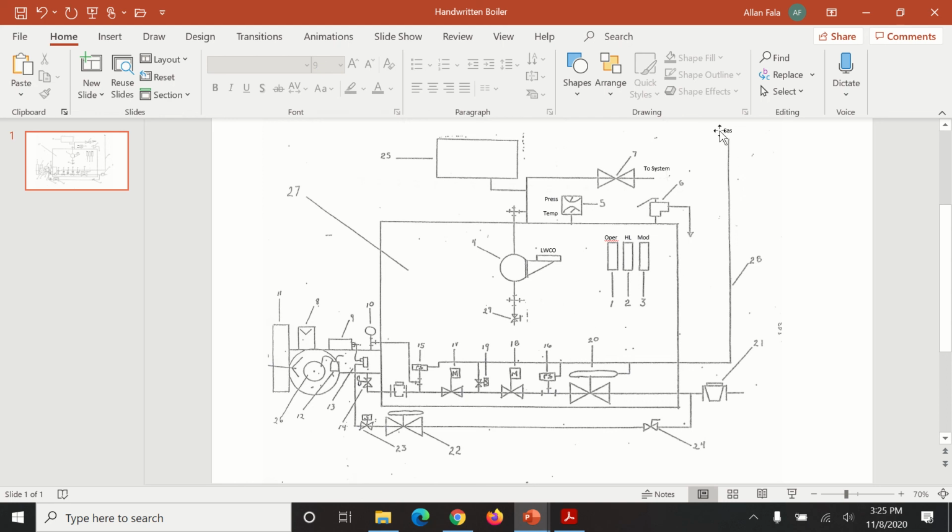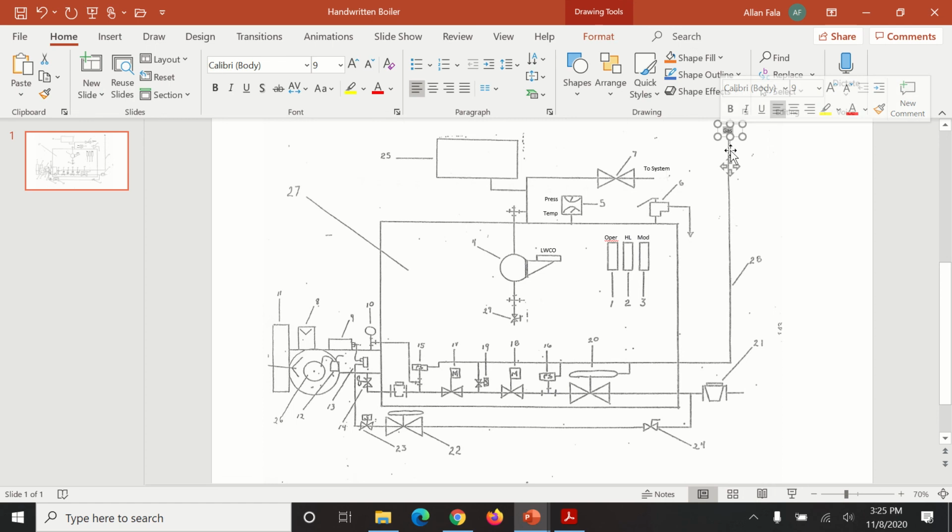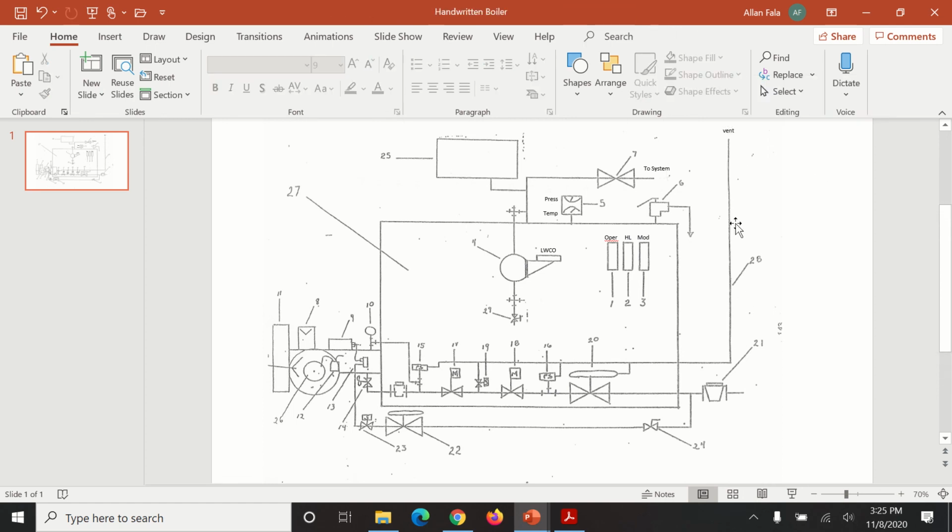Right up here, this is the gas line coming down. Oh, excuse me. I got to relabel that. That's the vent line. And the one thing I wanted to say about the vent line, this is not code anymore. Here you've got a vent coming off of the main gas regulator, a vent coming off of the low gas pressure switch. The vent valve on a boiler over 5 million BTU, you have to have 2 safety valves and 1 normally open vent valve.